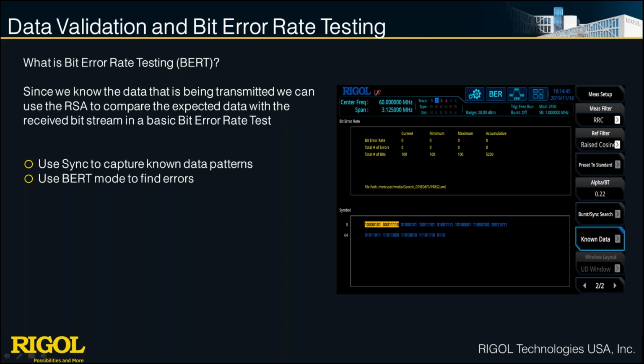You see the little yellow sequence of bits there is what we're triggering on in the spectrum analyzer. It's a repeating set of bits, and every time it triggers on that, it compares that 100-bit sequence to the 100 bits we loaded from the scope. So now we can tell for sure that we're getting no errors at this point.